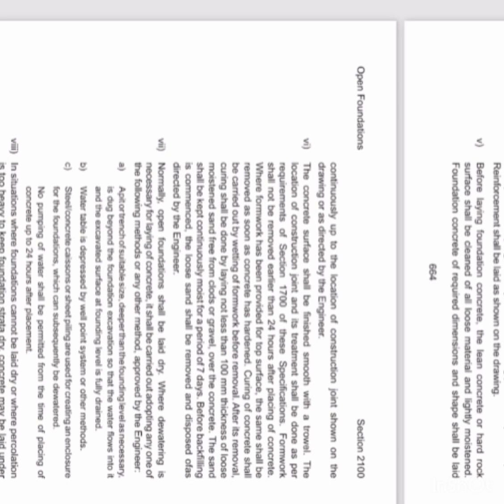Formwork shall not be removed earlier than 24 hours after placing of concrete. Where formwork has been provided for top surface, the same shall be removed as soon as concrete has hardened. Curing of concrete shall be carried out by wetting of formwork before removal. After its removal, curing shall be done by laying not less than 100 mm thickness of moistened sand free